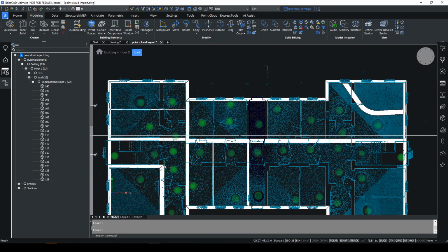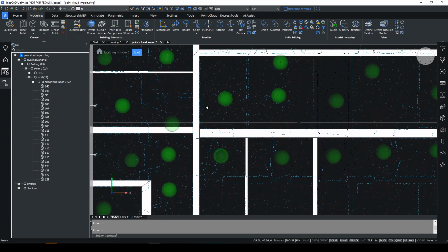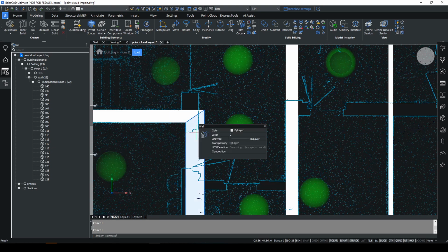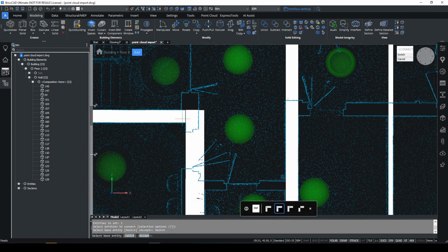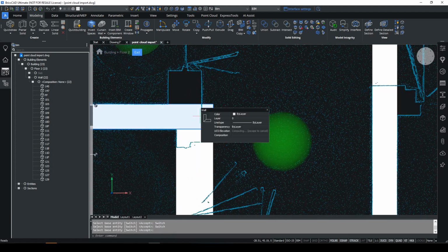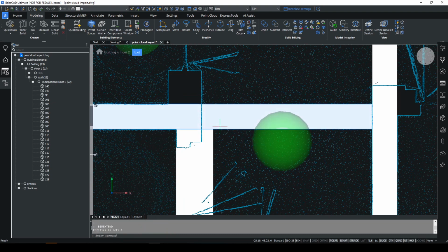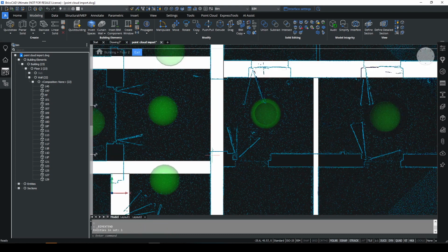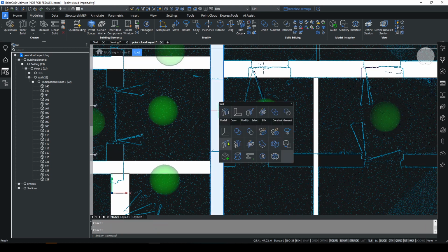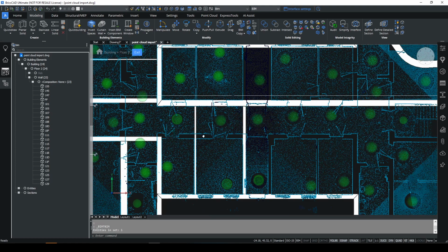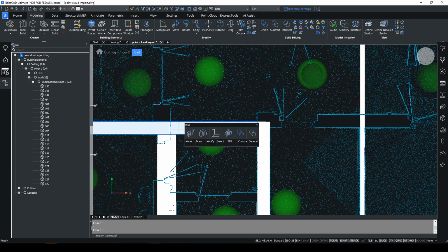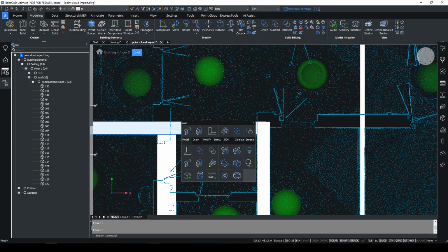Some of the other versions of what you can do here are run the BIM trim command. So let's change this to a version where we've got walls butting like this. Let's extend this along here. And now what we want to do is trim this wall where these two meet. So you hover over it, and instead of using BIM extend, use BIM trim, and that will cut these two walls here for us. You can see how quickly you can run through these. There's also a BIM slice command. So you would go here, click on BIM slice.